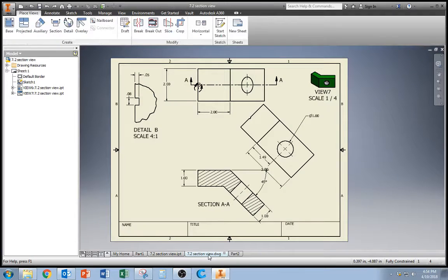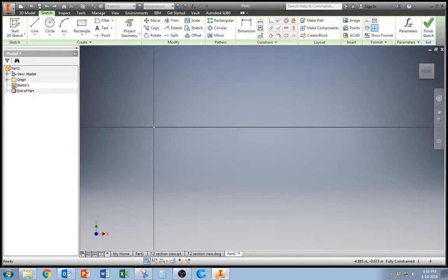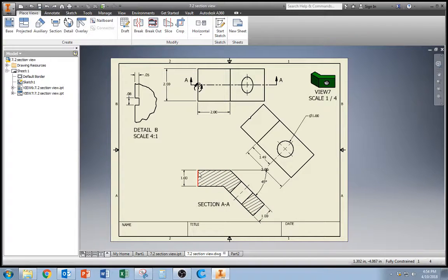And what we're going to do is we're actually going to make this outline first and do some extrusion. So let's take a look at our dimension. So it's 1 tall, it's 2 long. This part is 3 long, and this part is 1, and this is at a 45-degree angle, so we can actually type that in Inventor. Just plug it in, and then we're going to come back. We don't have a dimension for this, but that's okay because it'll just be where these two lines meet. So we'll have a parallel line, and that will meet this line.